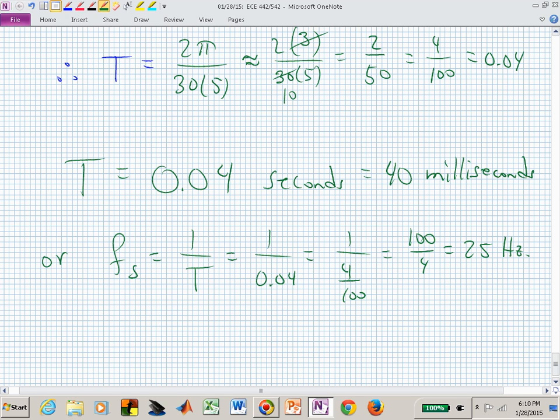We're not just going to see 2 points that the Nyquist would give us on some cycle of oscillation. And the closed loop bandwidth is roughly the highest frequency in our system. So we're wanting to see a lot of that shaking that's going on, or a lot of that waveform. That's why we're sampling much larger than the Nyquist frequency.